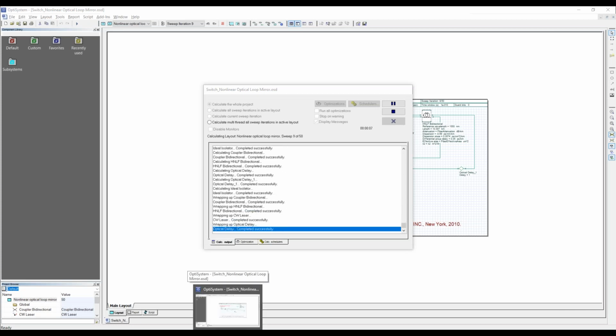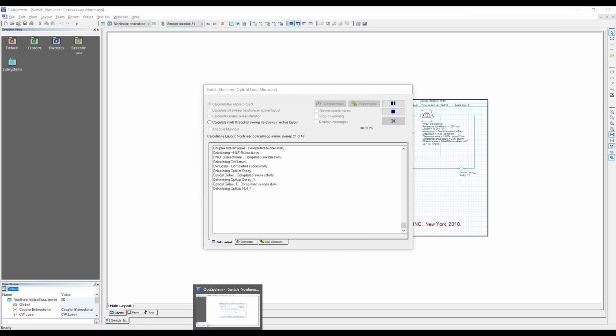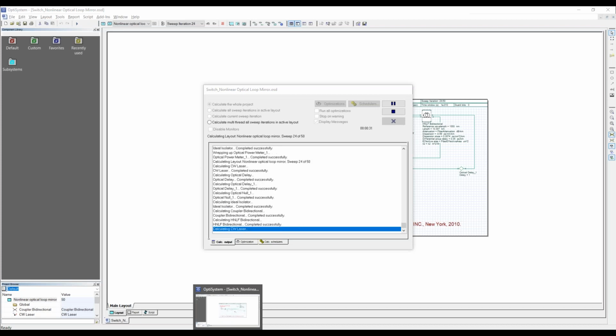During that, I'm going to look into some questions. One question asks why we are using, for example, an LED instead of a CW laser. First of all, the laser would be more expensive to use, and the LED is much cheaper. This is the main advantage of using LED. Plus, if the LED is centered at a certain frequency, the grating has to match within that frequency to detect it. If it is off, then you will have trouble detecting the light, and you lose it.